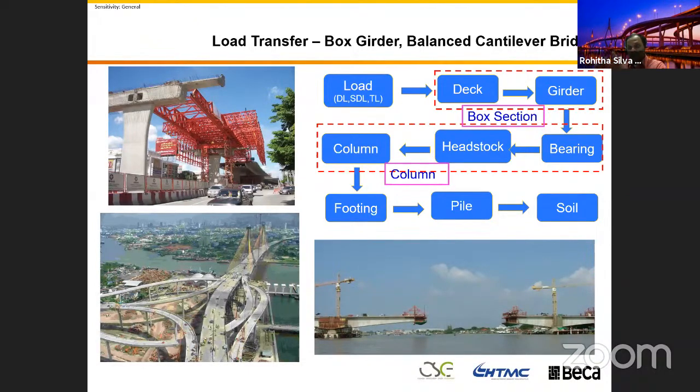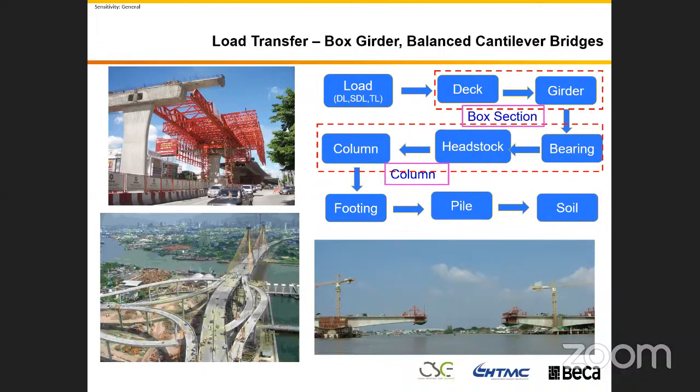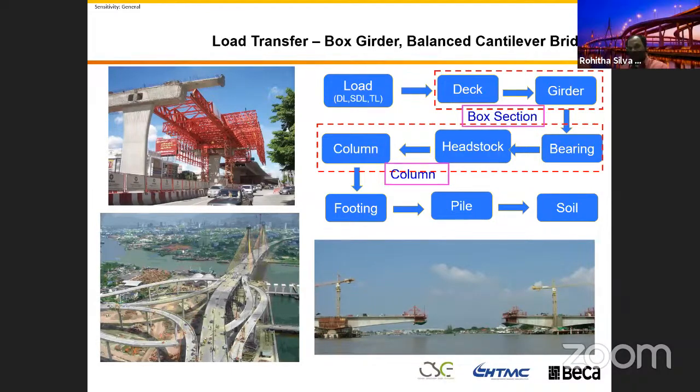When you design a building, it is different, because you know exactly the direction of the maximum bending, and which one is the major axis and minor axis. But in here, the flexibility will help, because that axial force is along the bridge's longitudinal direction. Because of that, we need to have that flexibility in the bridge.